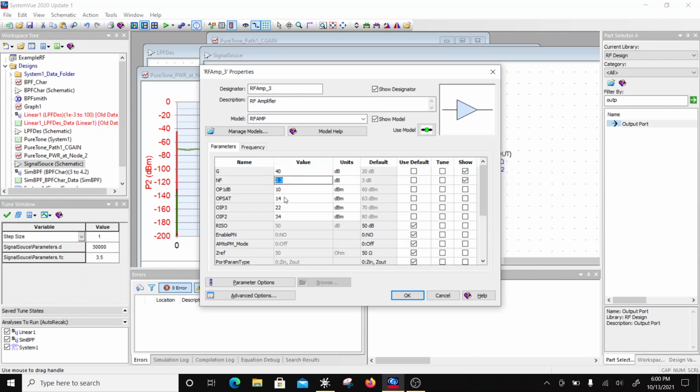Okay, and then the noise figure is really bad. This is a baseband amplifier, right? And OIP3, if I was to add 12 and a half plus 40, okay, 52 and a half. So basically this can handle very large voltages, right? So what should I put here? 12 and a half plus 40, 52.